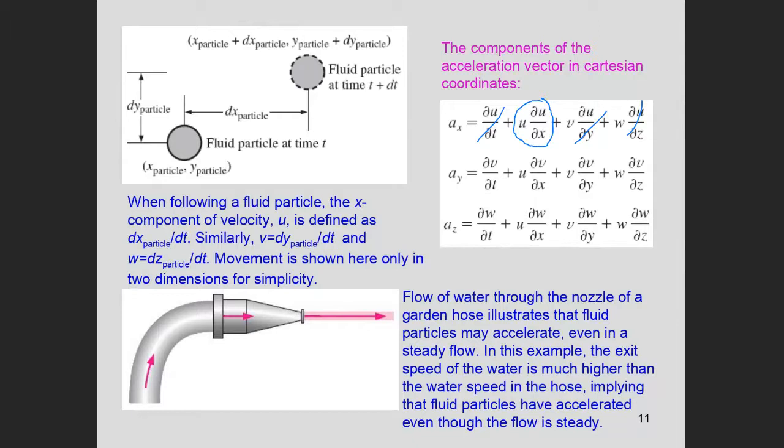Yes. For the example of the nozzle that we have been talking about, the flow is one-dimensional. There is no velocity v, there is no velocity w. The flow is steady, so del u by del t will disappear. Del u by del y will disappear. Del u by del z disappears. There is no v. So we only have this component, u del u by del x. Now this u is u average, which is u in plus u out divided by 2.